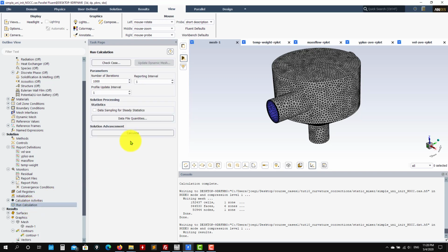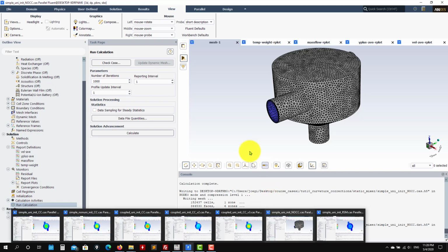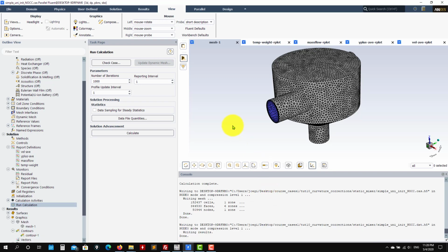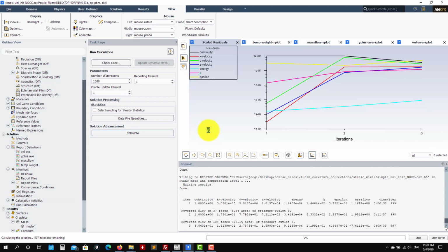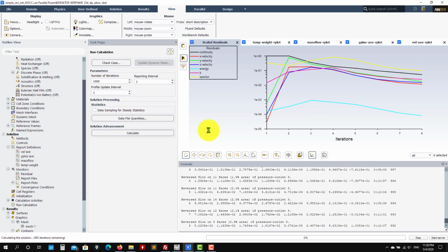And then we can run the solution. Put 100 iterations there, and let's launch it and see the behavior. Probably this will take something like 1,000 or 1,200 iterations, I don't recall, but let's monitor this behavior. I have many other solutions that I'm going to compare right ahead, but this one is just to show you the whole process, and then we're going to do some post-processing. I will launch it, and probably in 10-20 minutes we keep working on this one. So press calculate, and off you go.